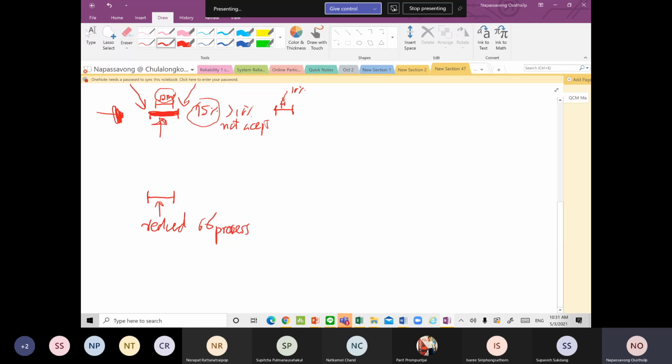So we have to reduce the variation of the measurement system to keep this ratio less than 10%. Do you get that? Because now our decision is that the precision is not good, right? The variation of the measurement system is too large.